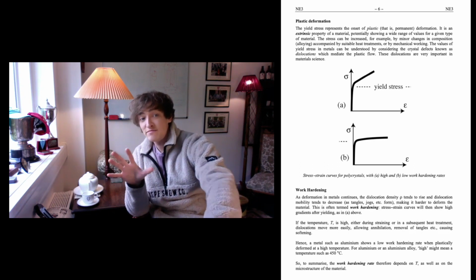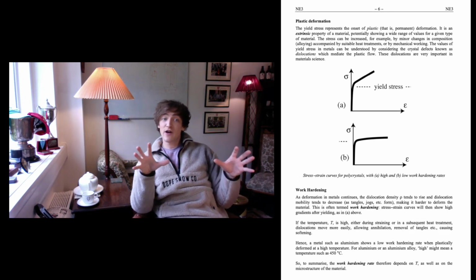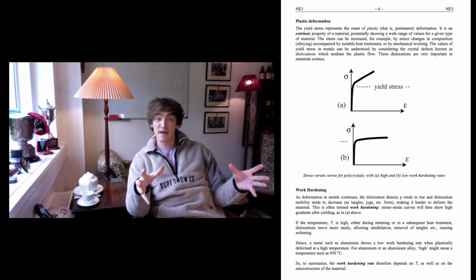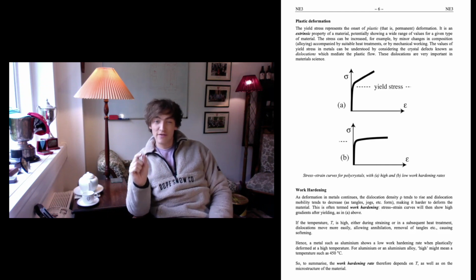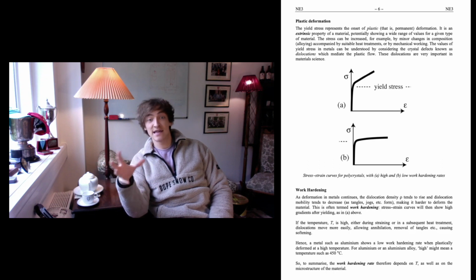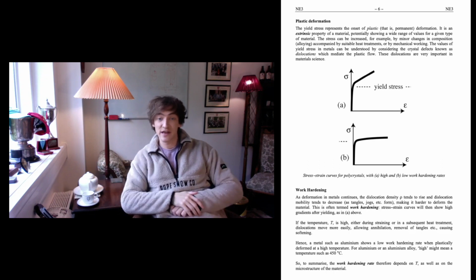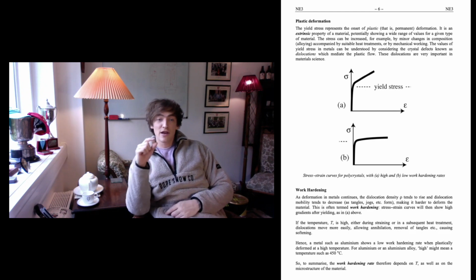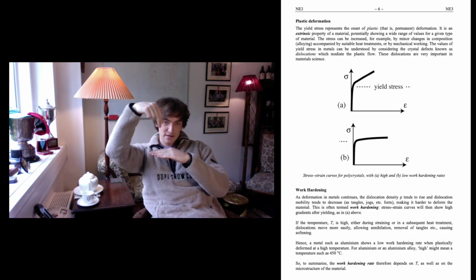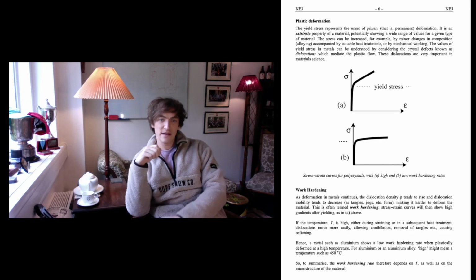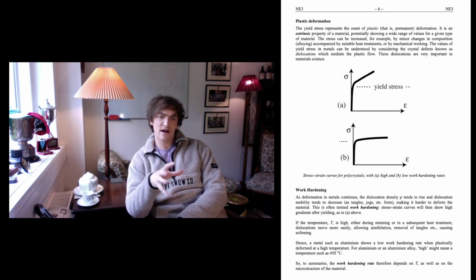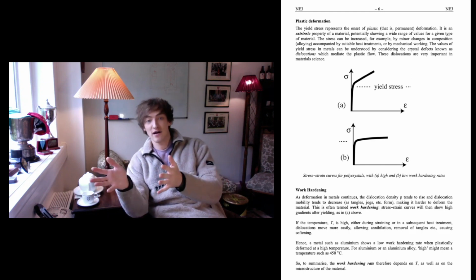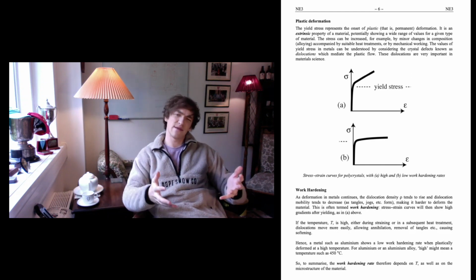Now there's some other terminology we need to get our head around. Some of you will have heard of material hardness. That's also a measure of the resistance to plastic deformation, but it's derived from a specific test method, far more convenient than, say, a tensile test used to produce these stress-strain curves. And it uses a localized compression at the material surface. You have a little diamond, you compress it. So they're not the same, but typically if a material has a high yield strength, it has a high hardness. If you increase the yield strength, it increases the hardness, because you're really measuring the same thing.